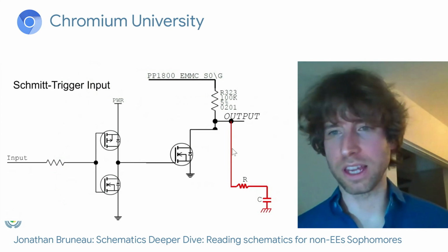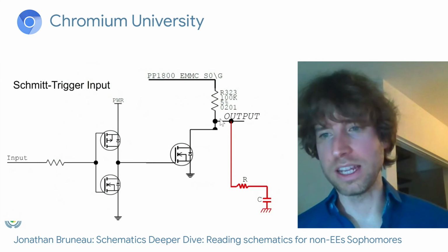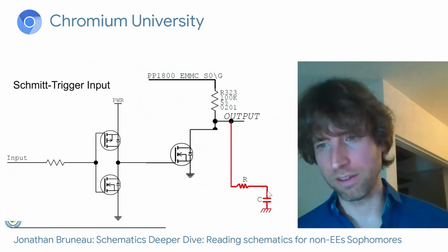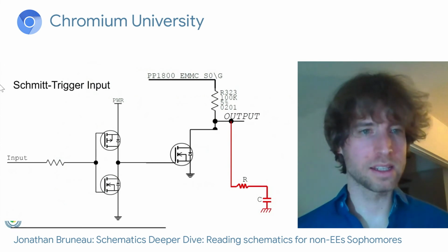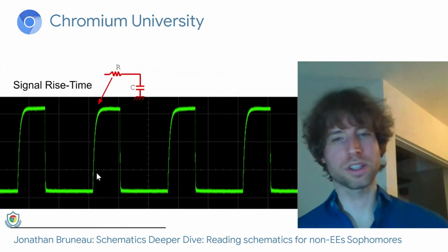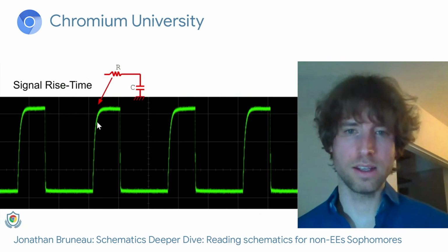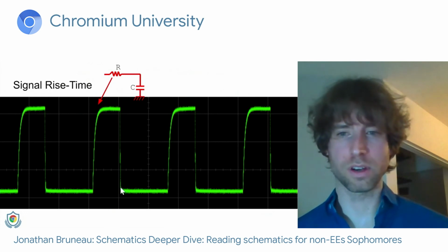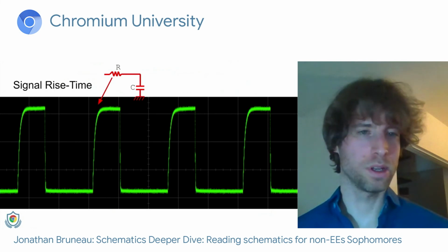And effectively, what happens is when the signal needs to charge this parasitic capacitance from the MOSFET, we have a low-pass filter here of sorts. So it takes time. So what you'll see is that the signal will rise slowly over time. And then when you need to discharge, it happens very quickly. But you get this ramp, so to speak.